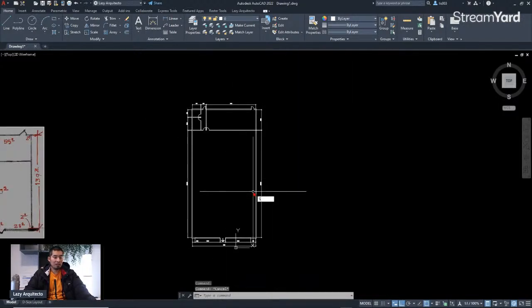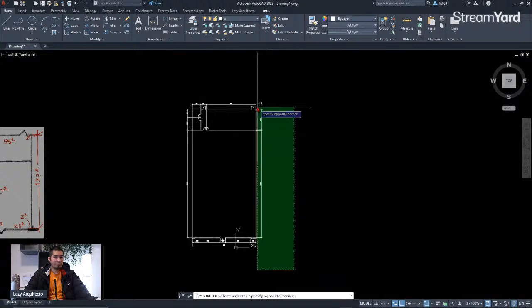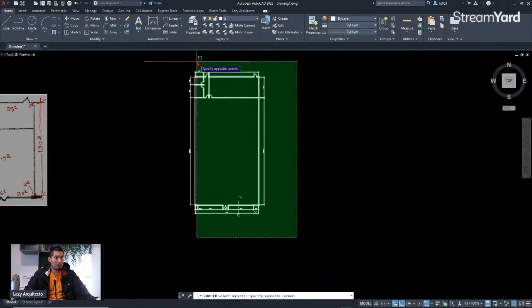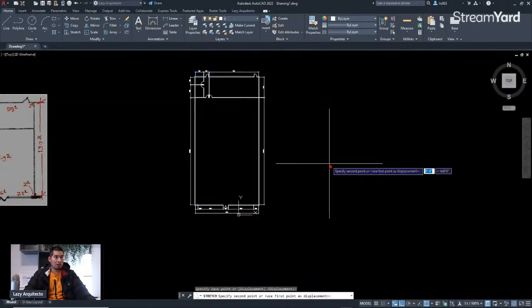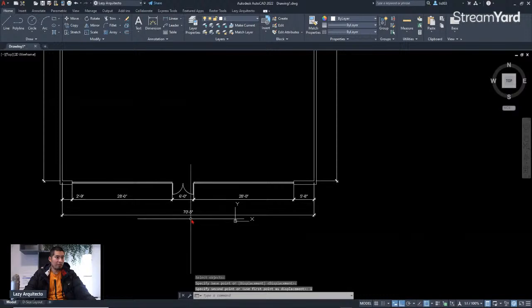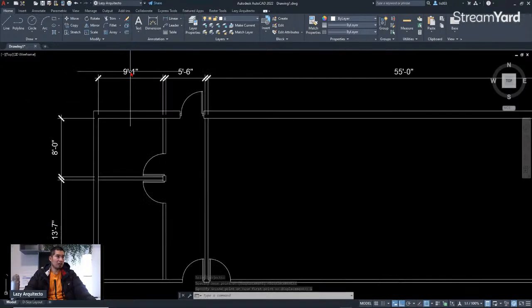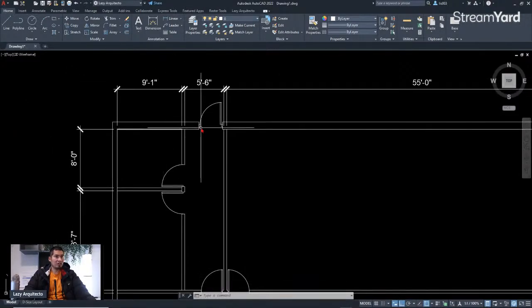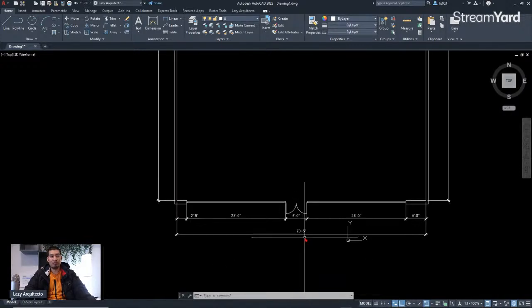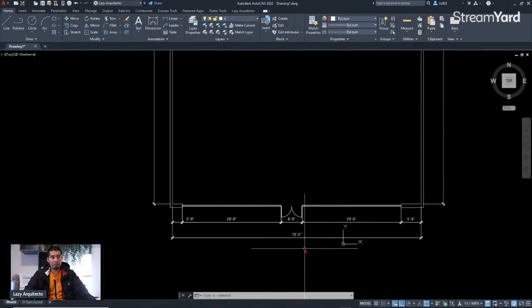And so I stretch, I'm gonna stretch it from here 1 inch, and this is 70 feet 5, and I'm sacrificing 1 inch over here, which is okay, because again, the most important thing is the overall of your building.